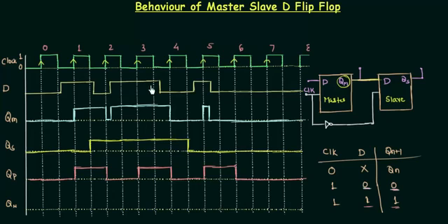The input signal is given here. Now finally the last waveform is for the negative edge triggered flip-flop, and it is very important. We have to draw various results from this. So let's try to find out the output of the flip-flop when it is negative edge triggered. We will consider all the falling edges, and I will use some different color for this purpose. Let's use white for this, and you will see some very good thing in a minute.